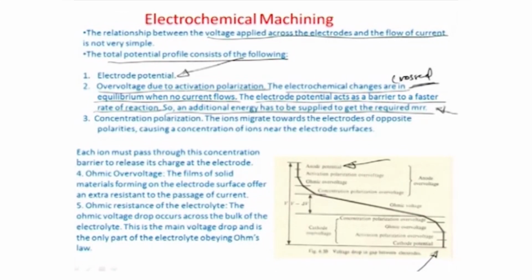Okay. So, this is the over voltage therefore. Whenever you are planning a certain voltage resulting in a certain current, you will have to accommodate for these over voltages and supply a slightly higher voltage, so that these losses can be taken care of while doing electrochemical machining.